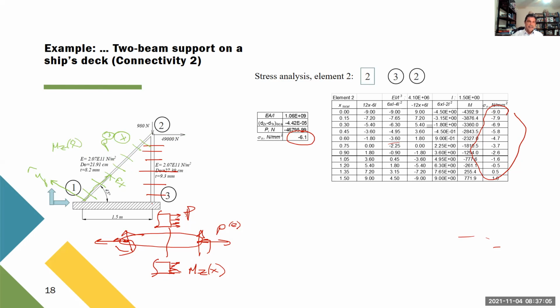And according to the variation of the bending moment, you have to calculate the maximum normal stress because of this bending. And in that case, you have to add in the side where the stress is positive. Why? Because on that side of the section, that stress, which is positive, will be combined with the stress from this value, which is also positive.